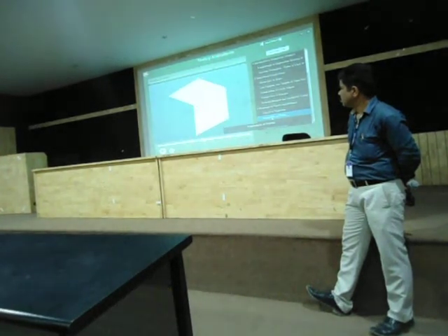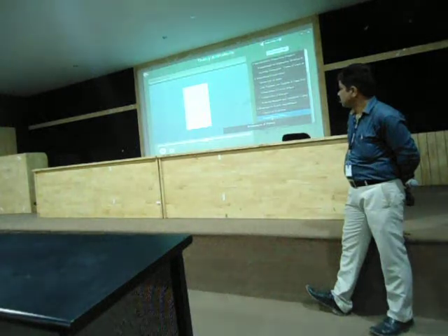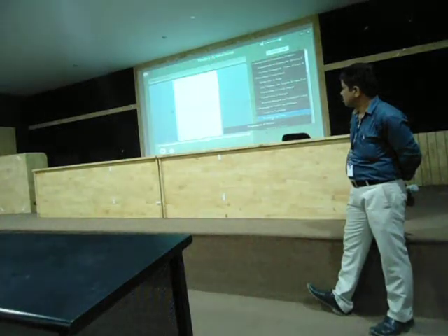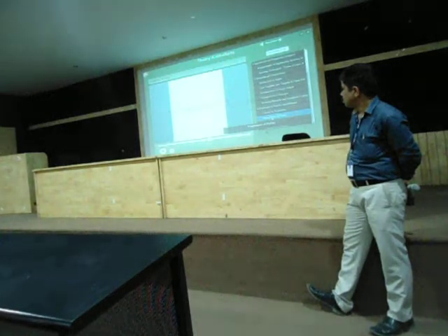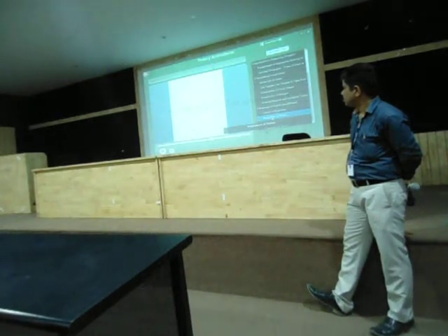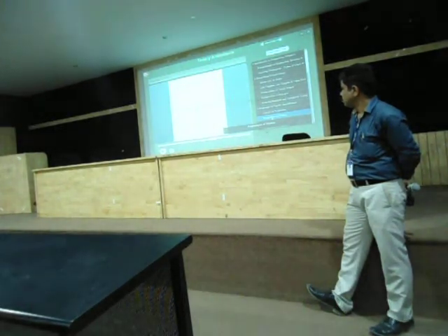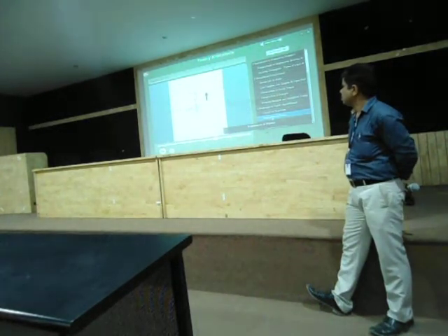So friends, now we have seen the visualization of the point. Let's see its construction. We repeat the step of drawing a horizontal reference line XY. Then mark a point C anywhere on the line XY. From point C, mark a point A dash at a distance of E units below line XY, and point A at a distance of D units above line XY.